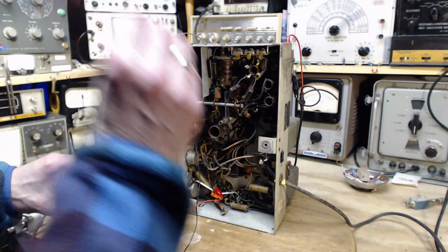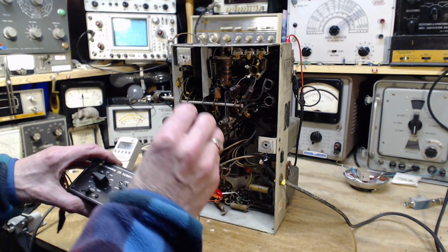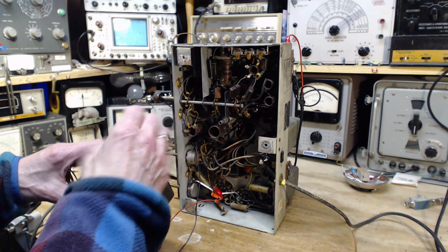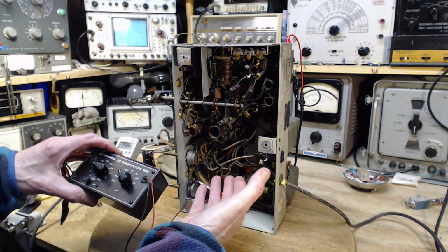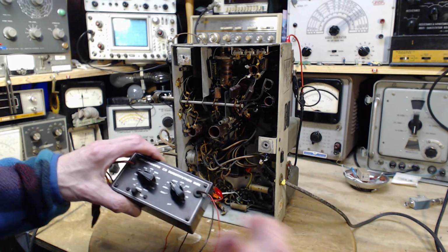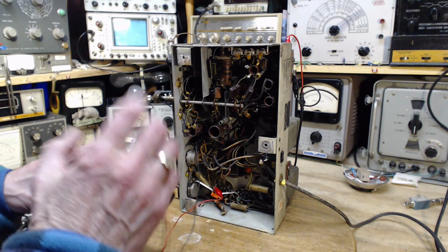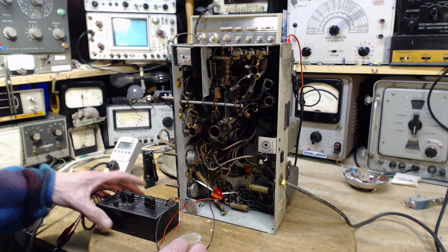So if the radio were working properly, aligned, all the capacitors changed, the tone range that would be coming at this point in the radio would be much greater, it'd be much more treble. And I'd appreciate it being cut back with a 0.005. So maybe I'm being fooled at this point.